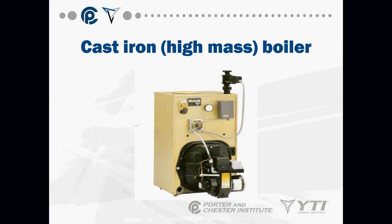There is your high mass cast iron boiler, and this is usually how they come when you order them. You actually have the ability to custom design what type of burner you want on it. It could be a Beckett burner, it could be a Riello burner, it could be a Carlin burner. You basically just order it as you want it. You size it up for whatever BTU output you need for a specific type of application.